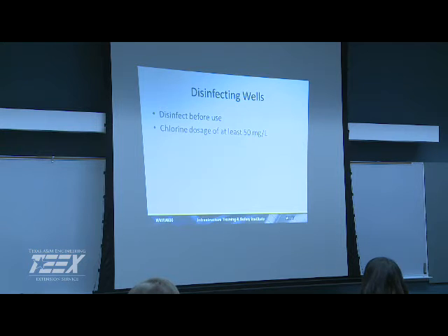We talked a little bit about disinfection. After we have a new well drilled, or if you've had some construction done to it, some work done, or you're having a water quality issue, sometimes you need to go back and disinfect it. But some of the wells there in the San Antonio area have to deal with the iron bacteria. So it grows a real nasty slime in there. You get some really, really funky water quality. So periodically you've got to go in there and dose your wells.